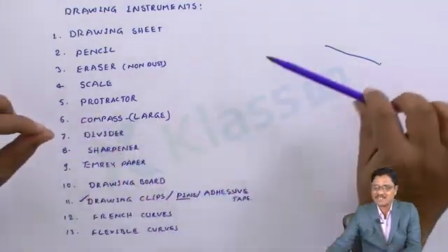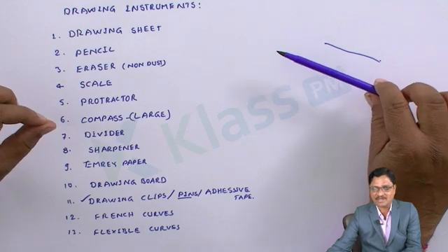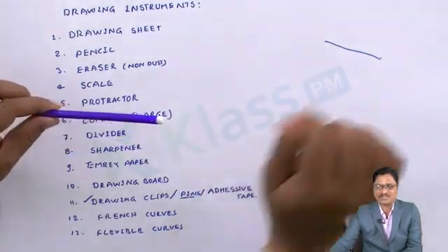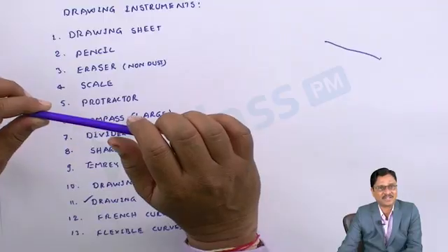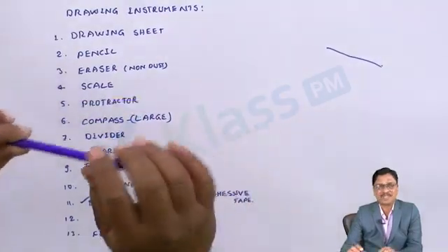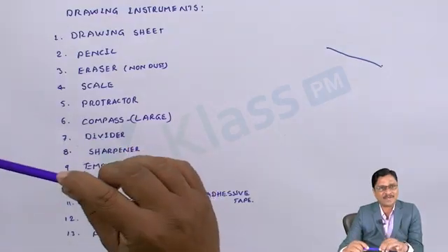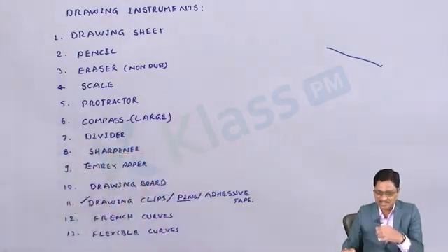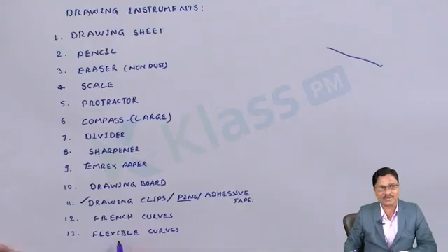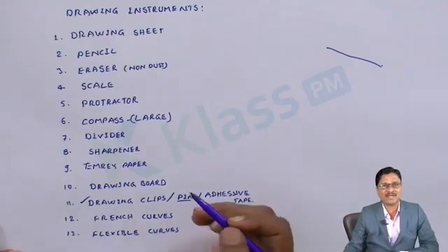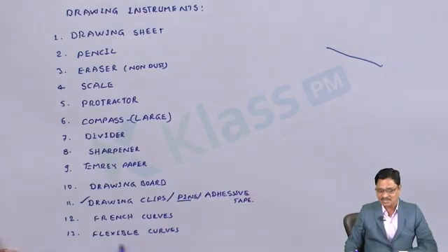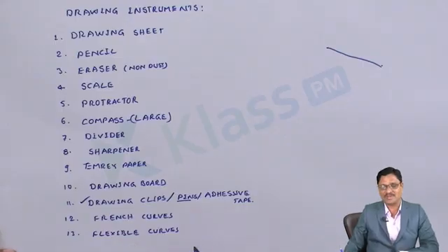So you can make the edge into whatever arc shape is needed. With that support I can draw the connecting lines along the edge. That is the main application of the flexible curve. After your work is completed, you can stretch it back by applying pressure. The flexibility makes it available to bend here and there temporarily as per our requirements. For that function we use the flexible curves.